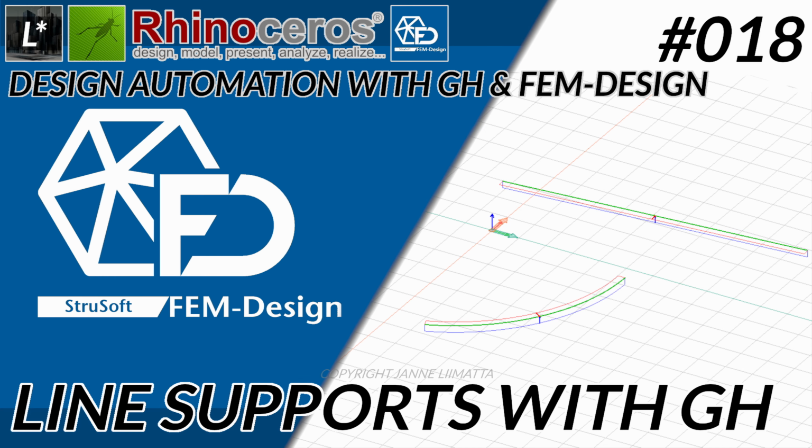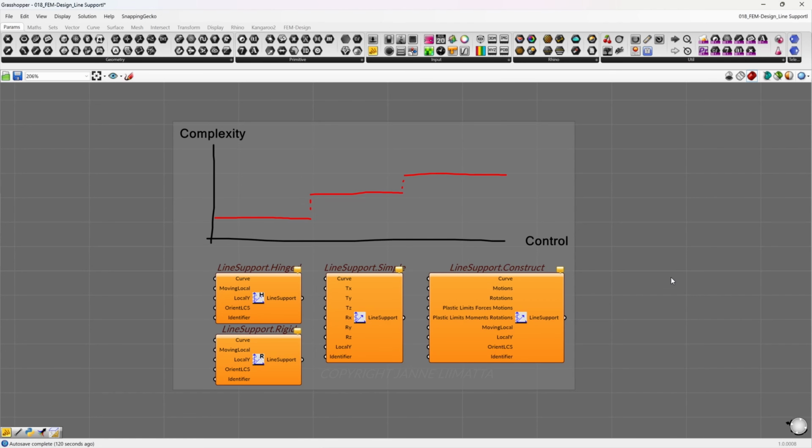The plate elements that we just created also need supports. Line supports can be created with these four components. The simplest ones are line support.hinged and line support.rigid. Then we have the line support.simple, and to get the most control, line support.construct can be used.